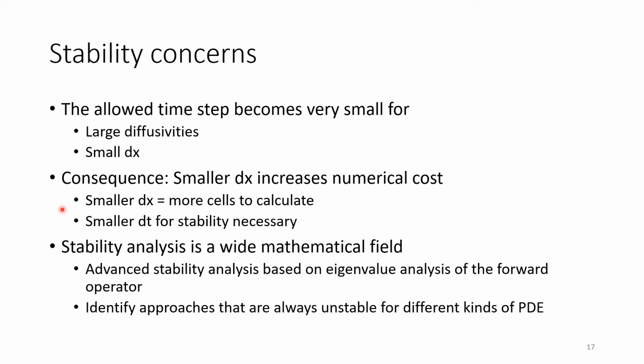also if you have an implicit model, which means it is unconditionally stable, still your accuracy is linked to your spatial resolution and in some ways linked to the maximum allowed time step of this CFL criteria. So many codes use this kind of CFL criteria or some other kind of stability criteria as a value to orient the time step possible for an implicit model. So this is something always to consider.